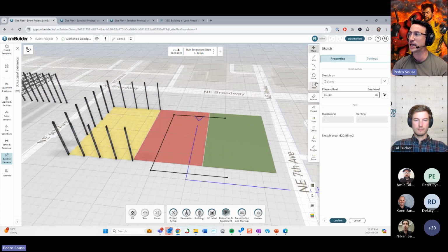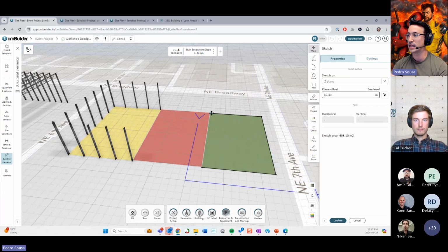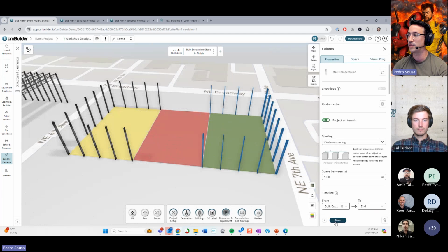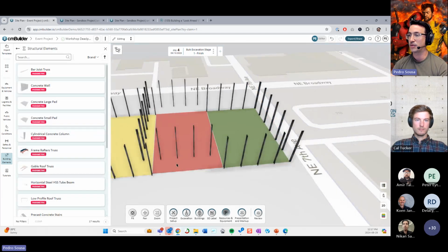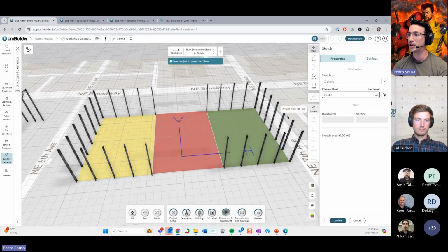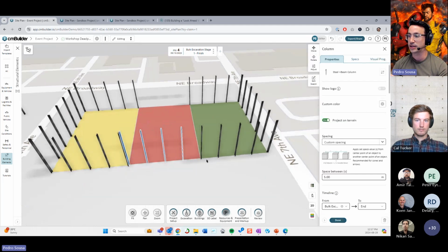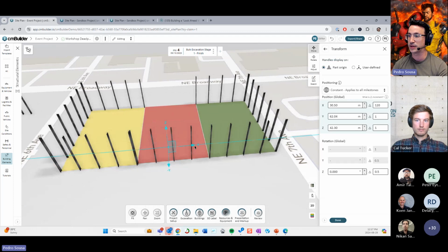And I'm going to edit the sketch, redraw, project this shape now, and then delete this one, and then see what is the result. And then I can see that I need to extend this line over here a little bit to create that. And then I'm going to copy paste that same element, edit the sketch, redraw, project this shape. And now I'm going to delete these lines, but I cannot yet have a sketch that has two independent lines. This is coming. And because of that, I'm going to delete one of them, and then we use that to create the spacing of the next one, right?